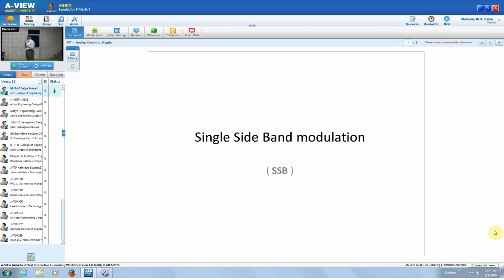Why? The power that we generate or transmit in the case of AM is carried by the carrier itself, 67%, whereas the information content is only in the remaining 33%. Therefore, this 67% is a waste, and therefore we have suppressed the carrier.